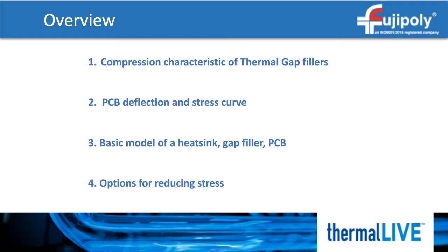You might be wondering why we would look at a stress-strain curve of a viscous material. The reason is because no gap filler is 100% compressible. Even a dispensable material is going to have its limits. Generally speaking, stress-strain curves are not linear, and gap fillers are typically highly dampened, so compression or stress created by compression is highly dependent on the speed that they are compressed at.